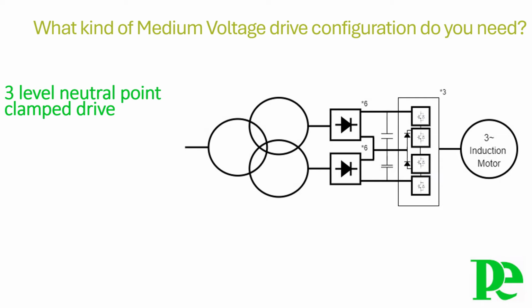The DC voltage is converted by the switching pattern of the IGBTs into a fundamental AC component with adjustable amplitude and frequency. For this kind of drive, the DC voltage is switched between 3 levels: plus, 0, and minus.